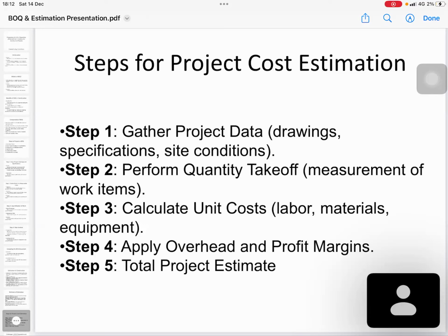As I said earlier, you have a BSR or HSR, so the detailed breakdowns are with you. Then you only have to apply the unit rates. For example, if 5 laborers are doing brickwork, 10 square meters, you have that breakdown in the BSR. And sometimes you have to increase the percentage according to the difficulty of the work. Then they apply the overhead.